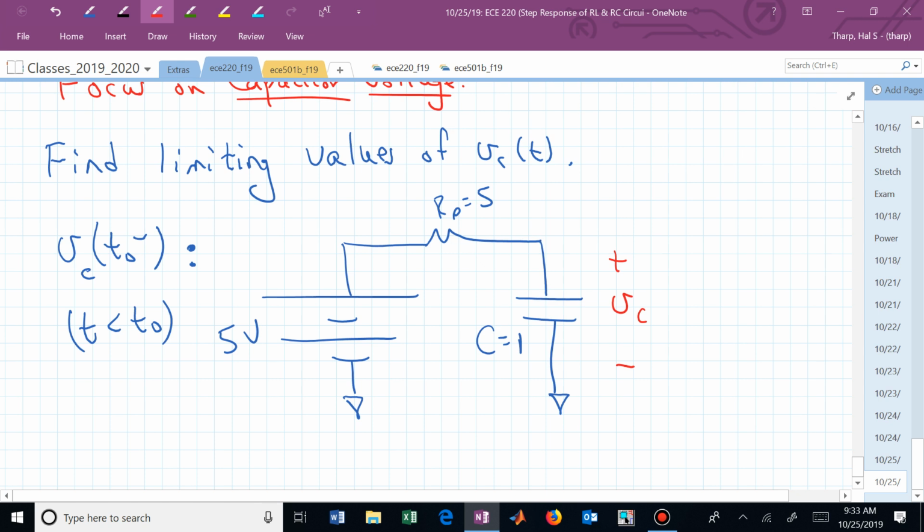What happens to that capacitor? It's now in a steady state, this circuit. It's excited by a constant input. What's the capacitor do? It charges up, and what does it do when it's fully charged? What happens to these variables? What happens to the voltage? Is it kind of rocking back and forth? It's constant, isn't it? What happens to the current? It's 0. So this capacitor opens once it's reached steady state.